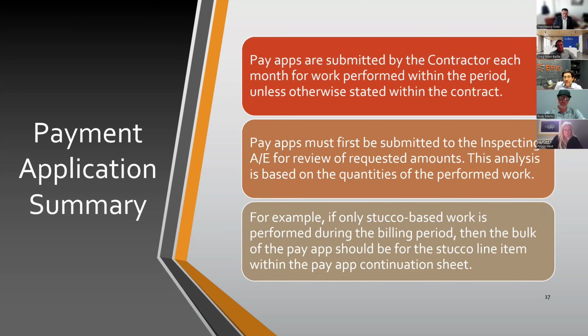But if I am inspecting and taking my final documentation, which I should be at the demolition phase, and I count that 2 square feet, 2 square feet goes on my inspection log. I should see on the backup a corresponding 2 square feet on floor whatever from the contractor. If I do not, raise the red flag. There shouldn't be a deviation at that point in time. The exposure has already occurred, and that is the extent of the repair.